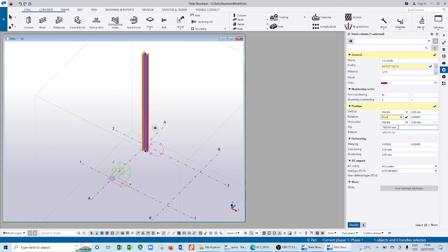After that, specify the height. Where it talks of the top, it gives you the top level. What top level do you need? So I can find from 0 level. From 0 level, it will be 6 meters. So I put in 6,000, yeah? Are you there? Then the starting level, the bottom, it had already put 450 for me. Then what I do is I put 0, because I want it to start from 0.